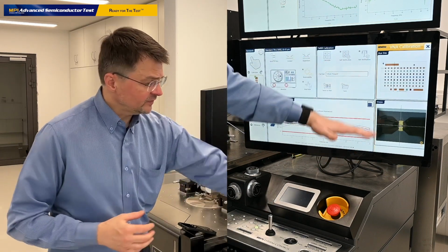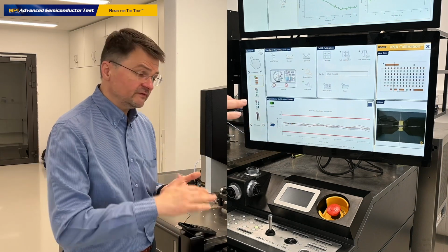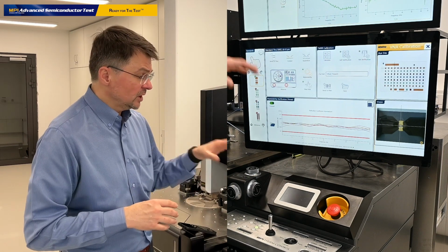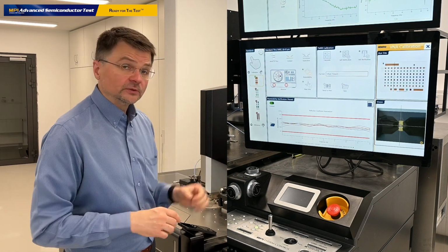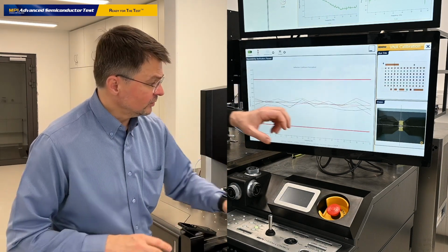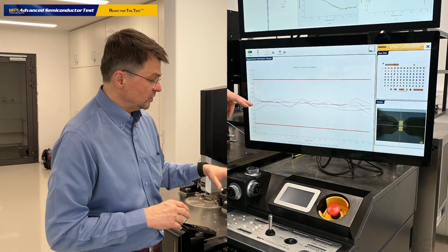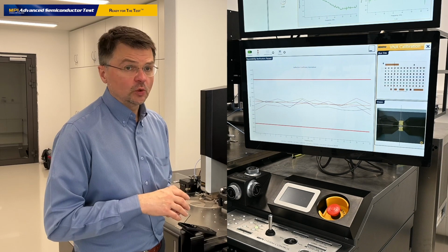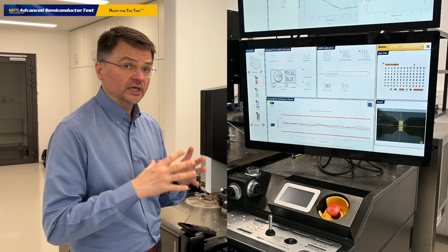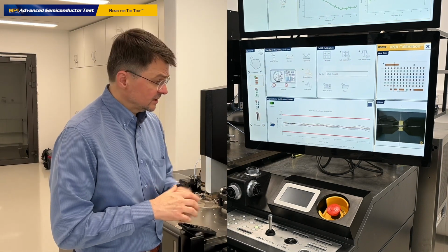What we observe here are the results of the repeatability test. This is the magnitude difference between the reference sweep, which was the first one, and the 5 other sweeps that Calibria took on the same calibration standard, on the same through, with just 10 frequency points, and we see that all repeatability data are within the margins that we set up for this type of measurement, which is plus minus 0.01 dB. It's very stable, repeatable data. We can conclude that the contact is good, and the data measured of this calibration standard will be consistent.